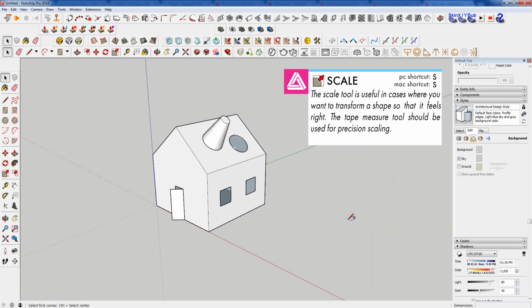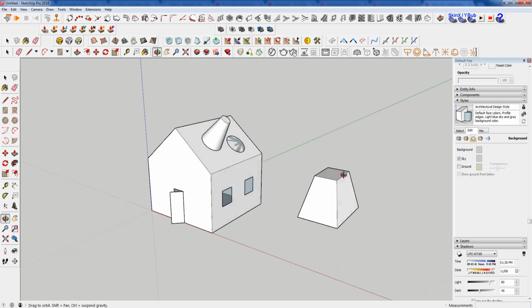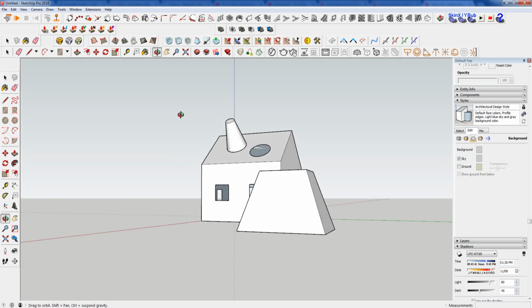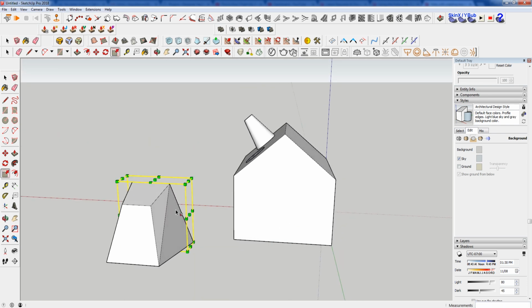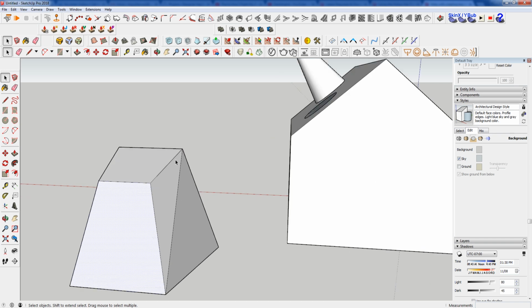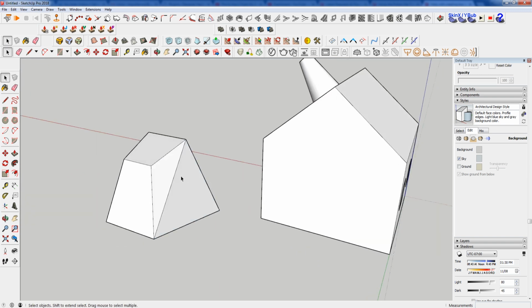And that goes with anything. If I quickly draw a cube here, select this top shape, press S for scale, you start to get these shapes. So this is more of a pyramidal shape, and I can do that with any face. So it starts to make the geometry sort of come to life. And maybe I don't want this hard edge here, but if you delete it, because that's not a planar line, it'll look kind of wonky, or it'll delete both faces because it's not planar.